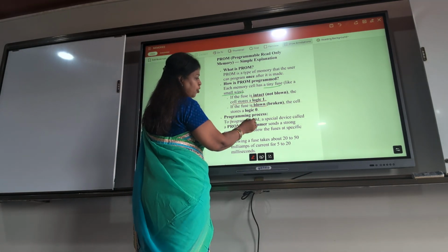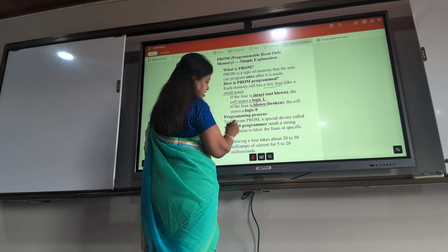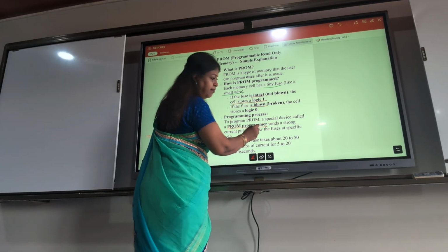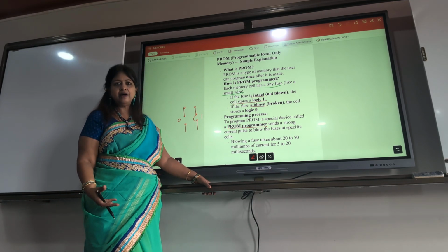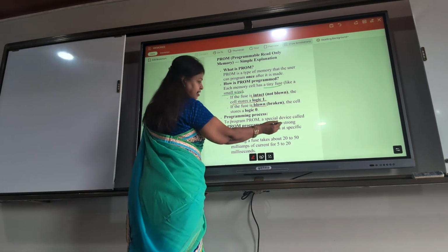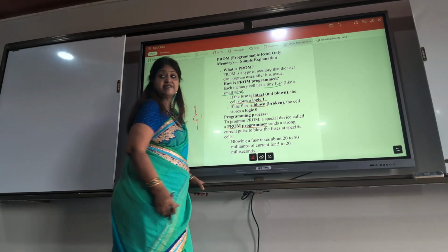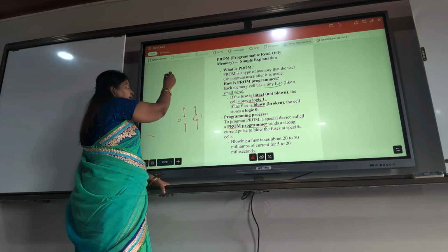Programming process. To program a PROM, a special device called a PROM programmer is used. You have to buy that. The company should buy that. And it sends a strong current pulse to blow the fuses. So initially, all are connected.